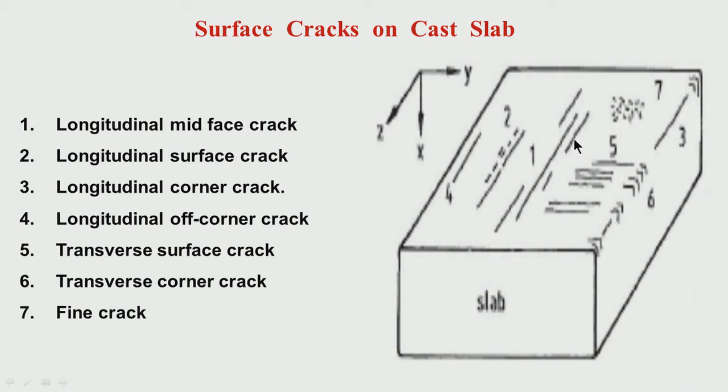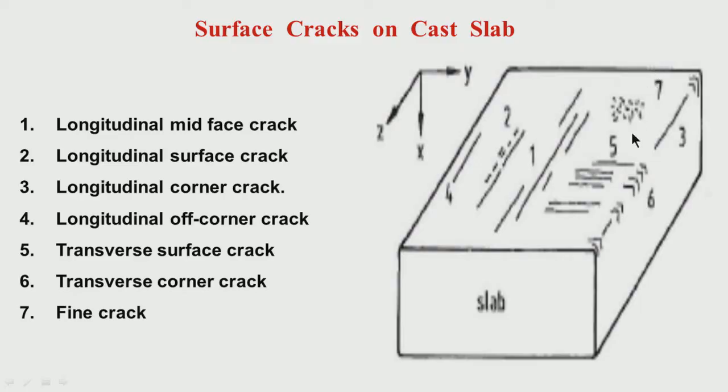Strain can be during solidification, as I mentioned, you can have strain at different points of casting, at different locations of the caster. You can have, due to bending, mechanical strain. Then there is shrinkage. In shrinkage, the direction will be away from the cast front.